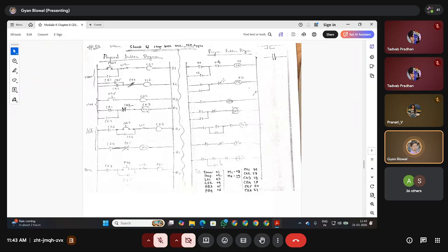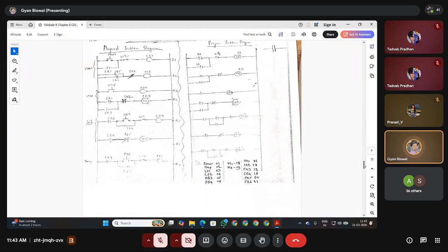In many applications, for better safety operations, most of the time we keep the stop button as normally closed. The stop button always remains energized if it is a very critical operation, so that as and when needed, there is no wastage of time to energize the stop button. You can start straight away and execute that task. The automation, the controller, will do that job. So if the start button is normally open type and the stop button is normally closed type, the answer will be a little bit modified. Be careful about that. I hope there is no confusion.